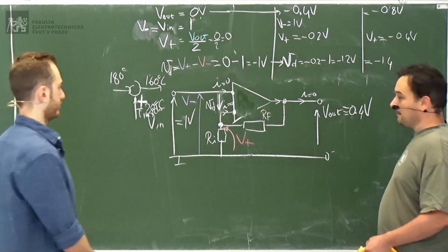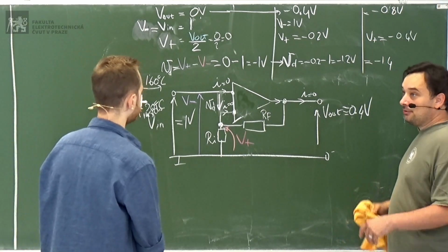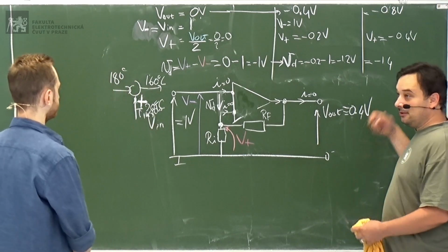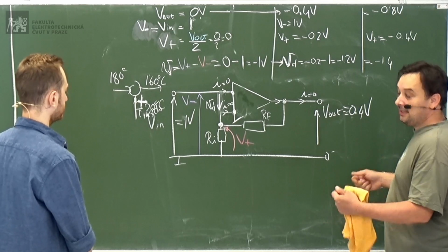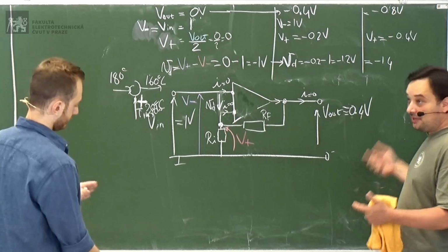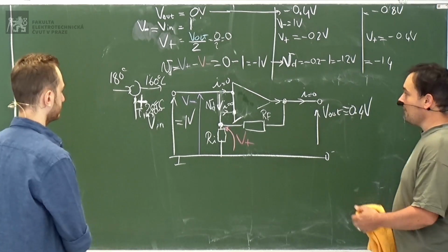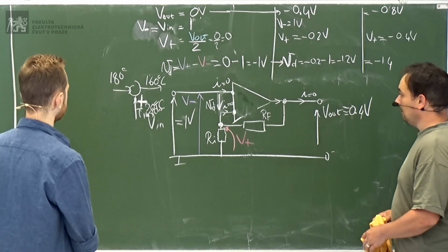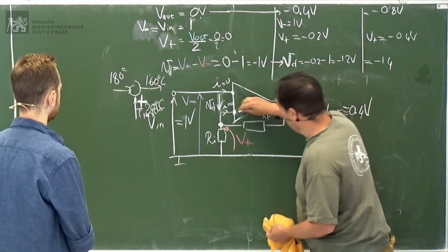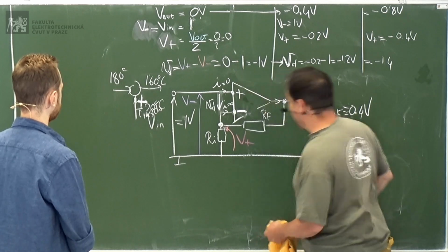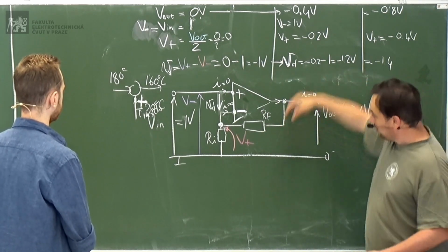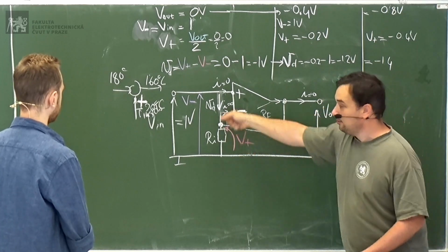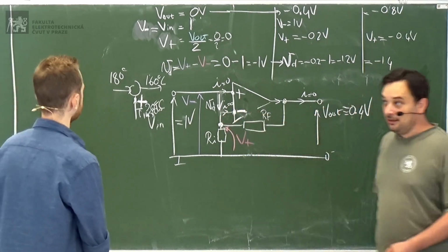Yes, okay? It won't converge. In order to converge, you have to subtract your reading from the set point in order to get 0 if they are the same. Okay? And so that's why, when you have an operational amplifier, always the feedback, what goes from the output to the input, should be connected to the negative.